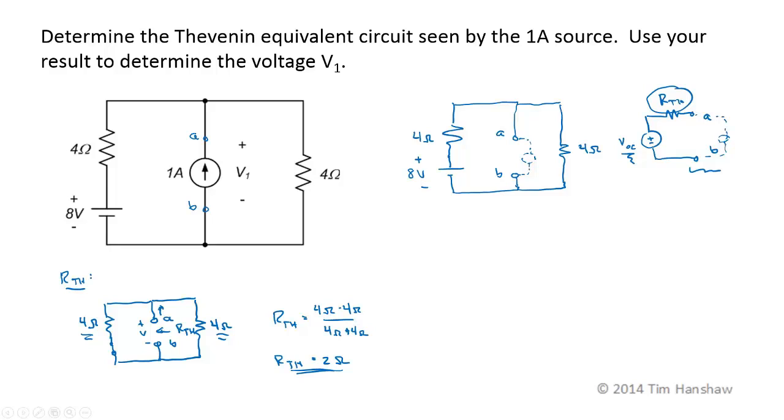Now, as a completely separate problem, we can find VOC. Now, we redo our circuit. From here, I have a 4 ohm resistor. Put your sources back in, so 4 ohms plus minus 8 volts. Terminals A and B are here, and this is also a 4 ohm resistor. Now in this drawing, terminals AB actually do form an open circuit, so there's no current through here. I is equal to 0 by definition. Now we want to find VAB, which is going to be my open circuit voltage. I can find that by any approach that I want.